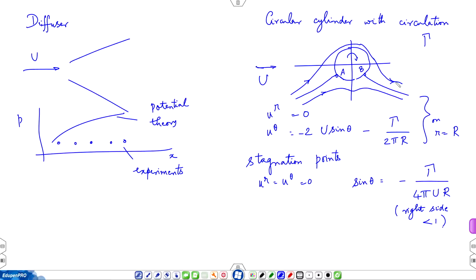Trying to show the symmetry with respect to the x-axis, above the cylinder and below the cylinder, there is a distinct difference which gives rise to lift acting on the object. Okay. In the presence of an adverse pressure gradient, you have left-right break of symmetry giving rise to drag. So here also you can locate points of adverse pressure gradient and then set pressure equal to constant.